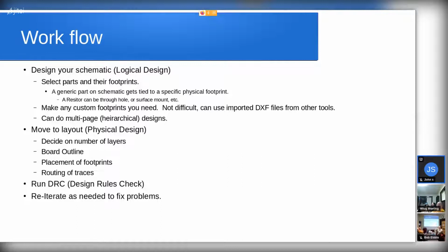So if I have a signal that has to jump over another signal, I have to drill down a layer, or go to the other side of the board, run it across, and come back up, depending. Or I just stay on the bottom layer, which is the nice thing with through-hole components like the old traditional resistors we're all used to, or DIP chips, dual inline package. You can easily run traces on either the top or bottom level, or even in the middle layers, because the solder will just go all the way through the hole and connect up to whichever connection was on a layer.